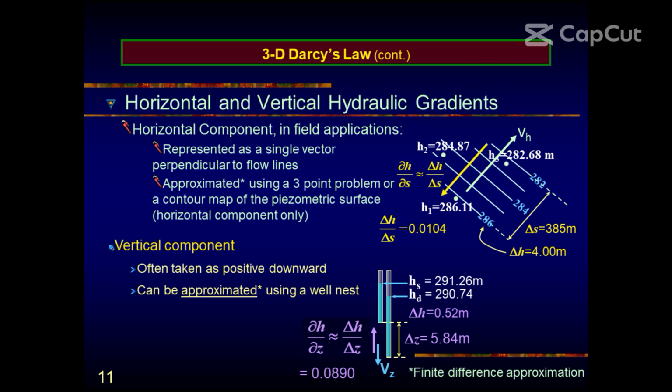Because if you remember, what did we say about the capillary fringe? That it is almost saturated. Yet, water is still not available for transmission to wells. The water in the capillary fringe is not available to wells. Because although it is almost saturated, the water is tightly held against gravity by the capillary forces, surface tension, and what have you. So it's not available to wells.